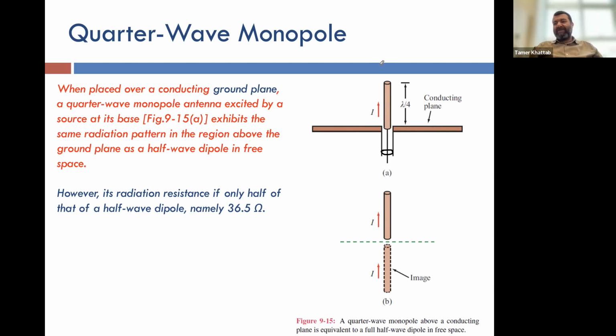And that's what you see in the antenna for your radio receiver at home, or the antennas used for cars, for example, the mobile phones on the cars, particularly for people who work in the Ministry of Interior or whatever. You have that long antenna because they use a low frequency, and accordingly their wavelength is really large. So they have only one wire. You don't see two wires coming out of the car. The reason is that they are implementing a monopole antenna, a quarter wavelength monopole antenna.